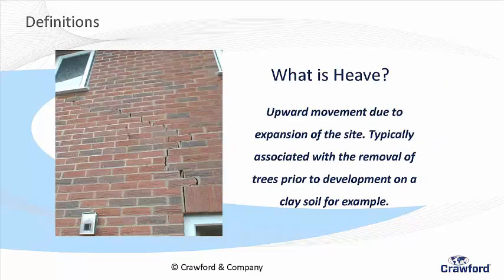Heave, just to cover that off, even though it's about 2 or 3% of the claims. Heave is, believe it or not, upward movement to the side. So expansion. And the only thing that expands is clay. No other soil expands, okay? So the soil like clay is going to expand. It's because something's been taken away. It's usually trees. Trees take water from the clay. As soon as you take a tree out, the water is retained in the clay and the clay starts to swell.